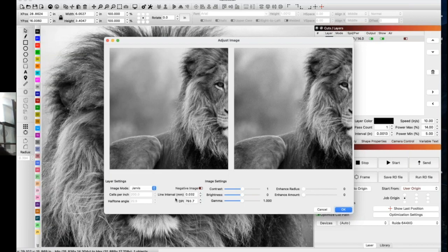Yeah, according to Thunder Laser China, on the standard 2-inch lens, the focal distance is 5 to 6.5, and the dot size is 0.099 millimeters, or 0.0039 inches for the standard 2-inch. So if that helps in determining your line interval, so that your line interval matches your machine. And focal distance is huge too.